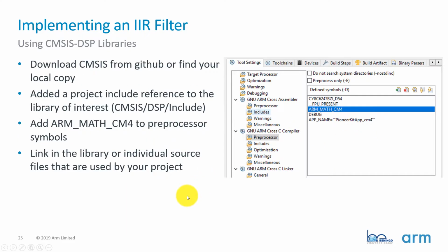And in most IDEs, what you're going to find is that you don't have to do a whole lot to get this to work. But as I mentioned, for example, if you use Keil, a lot of times this is automatically pulled in. If you're using something that's GCC based, you might have to do a little bit of extra work. Maybe CMSIS doesn't show up, or you have to dig into the compiler libraries to figure out exactly where CMSIS is located.